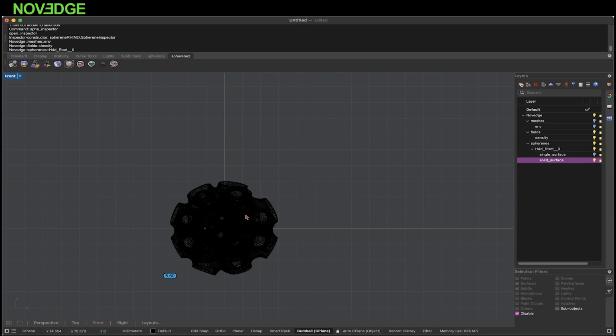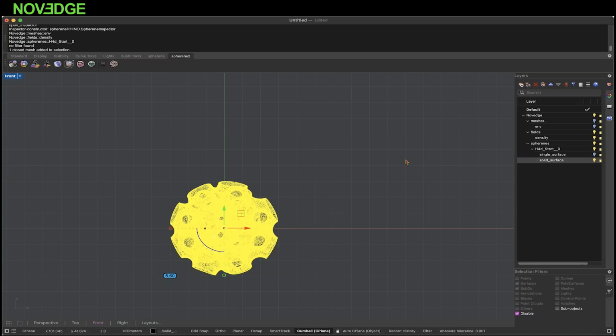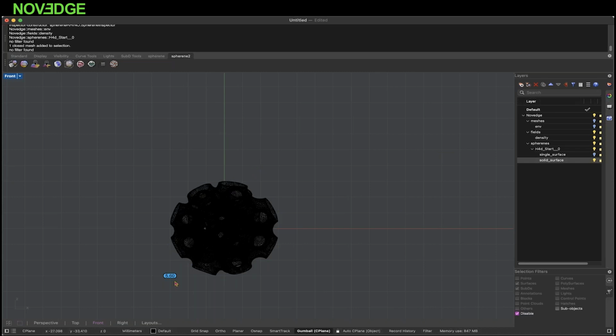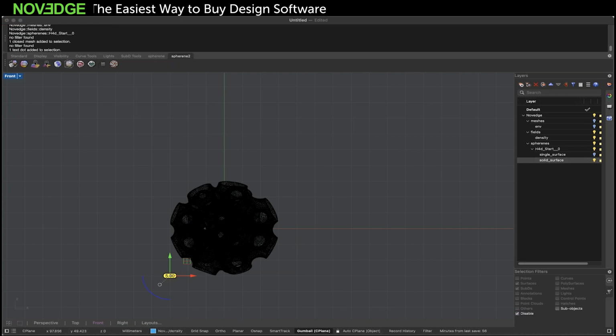The other one is, if you click any Spherene object, you see stats, and it's a bunch of stats you can get out. So we can filter it. What's the volume percentage? Boom, you see the volume percentage. And you can add how many holes it has, so the genus, for example. We have some values there. Clear the filter again to get the full view. If I want to change this value here, I just click on it. I can enter any value that I like, and it updates directly.